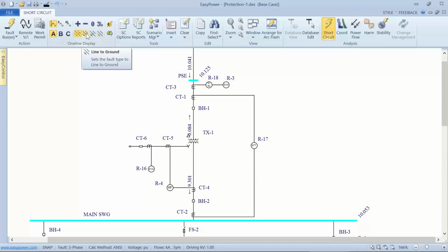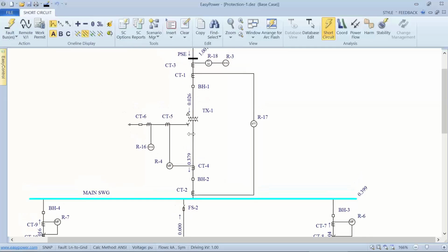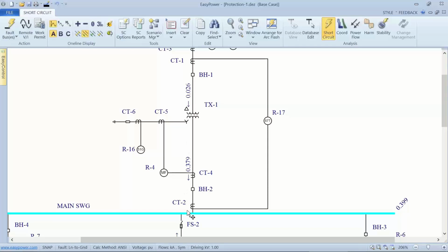Well, to look at the fault current, we're really talking about a line to ground or a single line or a dual line to ground. So if we select, and I'm up here on the second row, the type of fault to be a line to ground, we see the current that would be converging on each bus. And if we fall to just the main switchgear bus by itself, what this tells us is a number of valuable pieces of data. First of all, the worst case fault that we would see on the downstream side of the transformer is 379 amps.